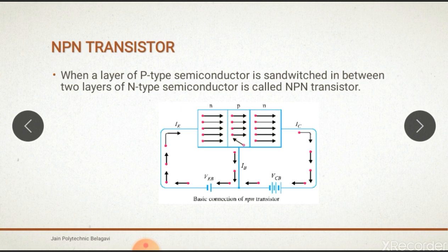First we will know how this will work. Here there is forward bias to the emitter base and reverse bias to the collector base. The forward bias causes the electrons in the n-type emitter to flow towards the base. This contributes the emitter current. These electrons flow through the p-type base. They tend to combine with the holes as the base is lightly doped and very thin.